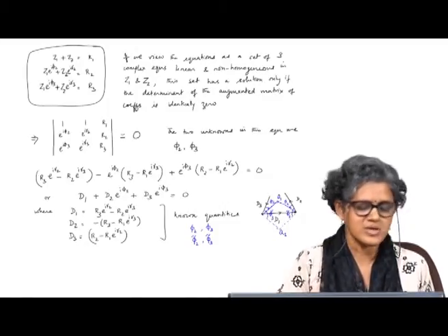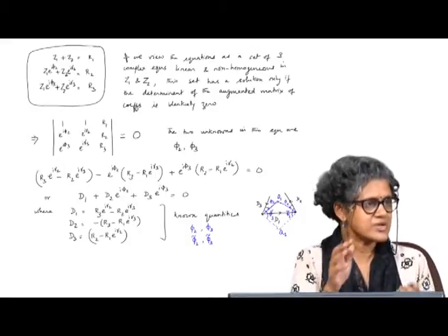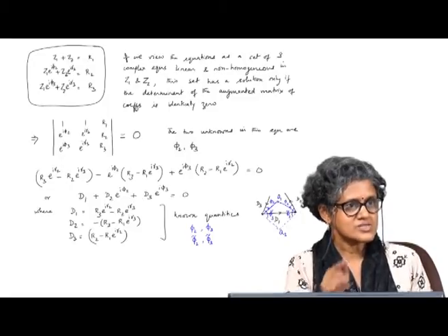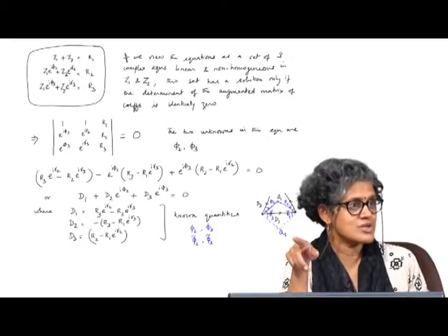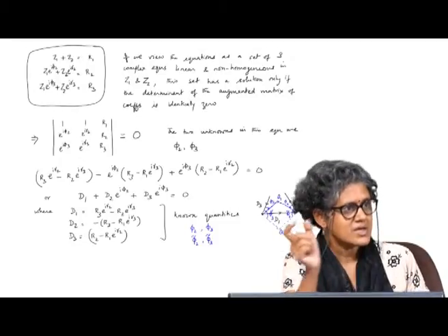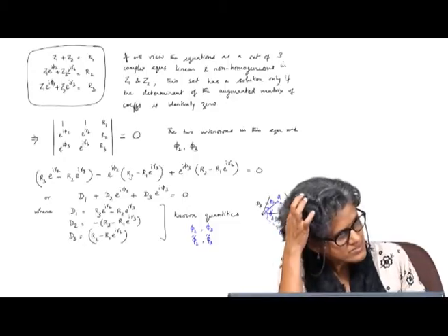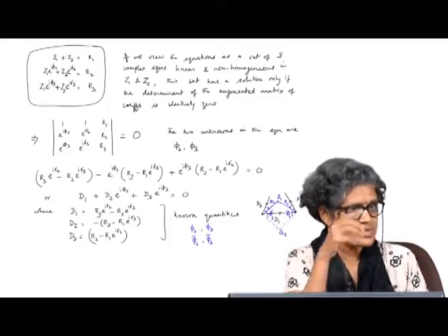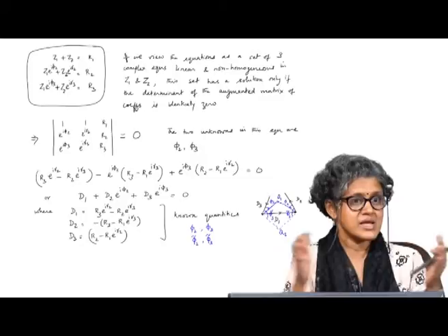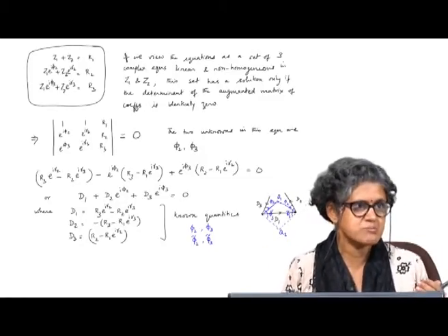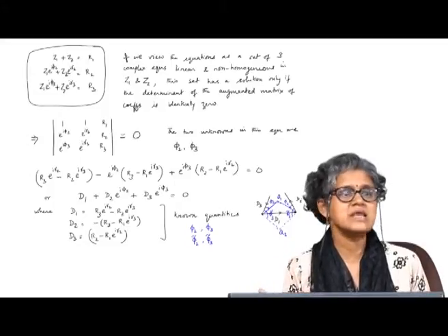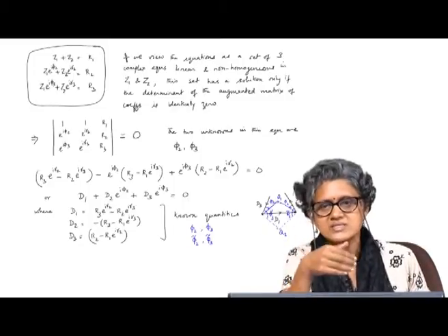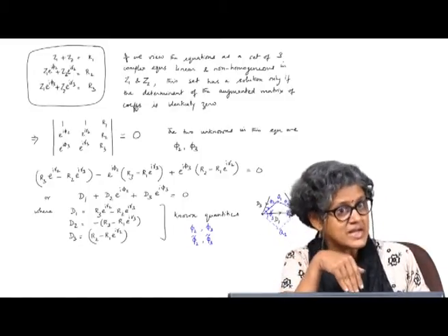what we are trying to do here, because otherwise it is rather difficult, you would have to expand it. See, d1, d2, d3 are also complex. So, it is not like your loop closure equation for the 4 bar, where you have real numbers multiplied by this. Here you have complex times complex numbers. So, you would have to expand this, separate out the real and imaginary parts, then eliminate one of the angles using the same thing, you know, cos and sine you square and add, but it becomes a very tedious procedure.